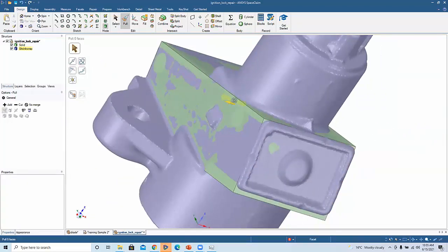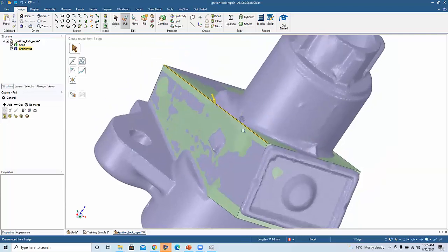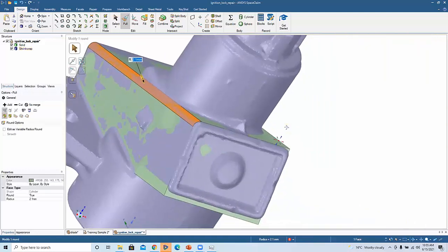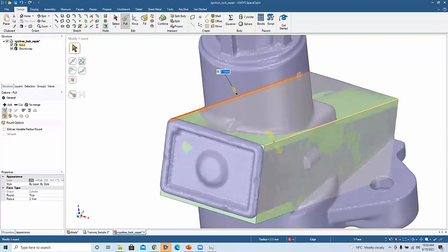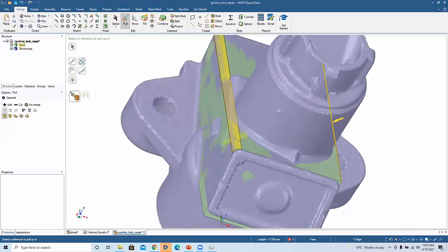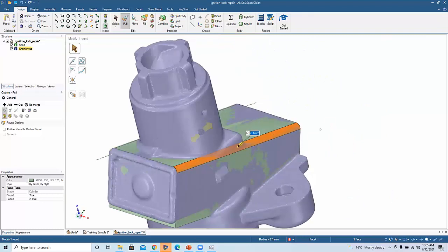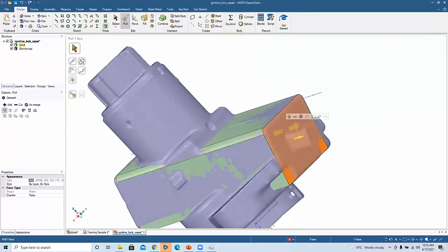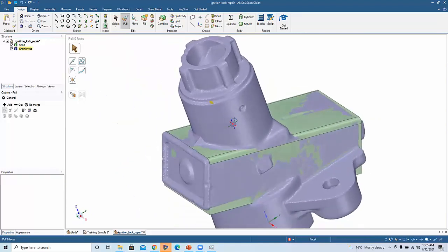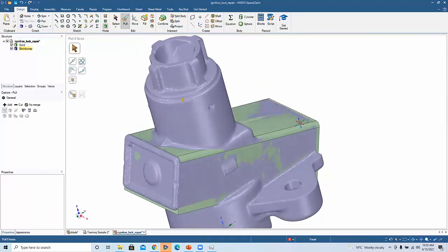is. So it's a very nice feature, not just for creating simple offsets of blocks, but I can even create maybe a round here on the outside. So I can just create an offset for the round. I'm going to use the UpTo command to match that round over here. And so I'm just using this to snap to the actual features in the model, to grab the proper dimensions right off of the mesh.